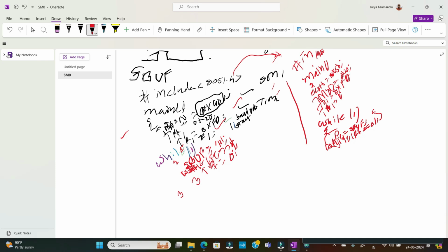We wait until the receive interrupt becomes 1, which indicates that data is received successfully, and then to receive another character we have to reset RI. Then immediately we have to make it 0 to receive the next character. So that's the only change in the program when compared to data transmission.